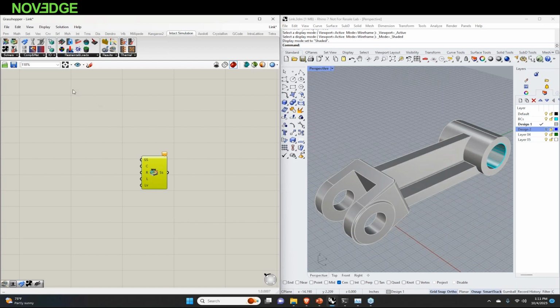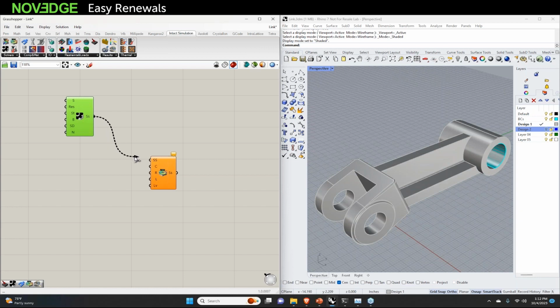The first thing we'll do is add the simulation settings. That is this tool right here in the solvers block, which is a little gear icon which has the basic solver settings in it. By default, it's set to a resolution of 100,000 elements, which is perfect for this particular geometry. It's enough to give us decent results. So after that's inserted, we'll just use the default settings. It's good enough for what we're doing right now. So plug that in, we're good, that's set.